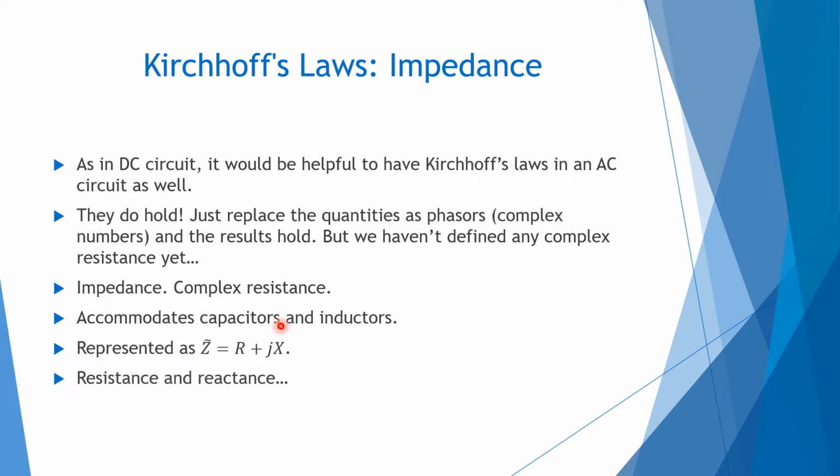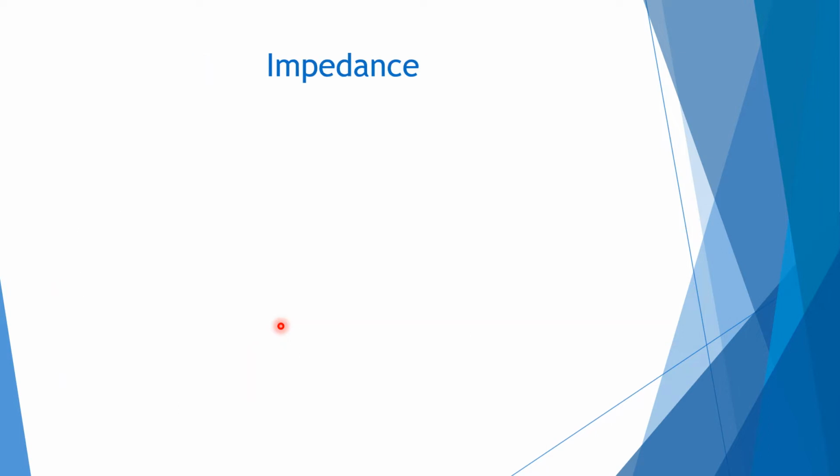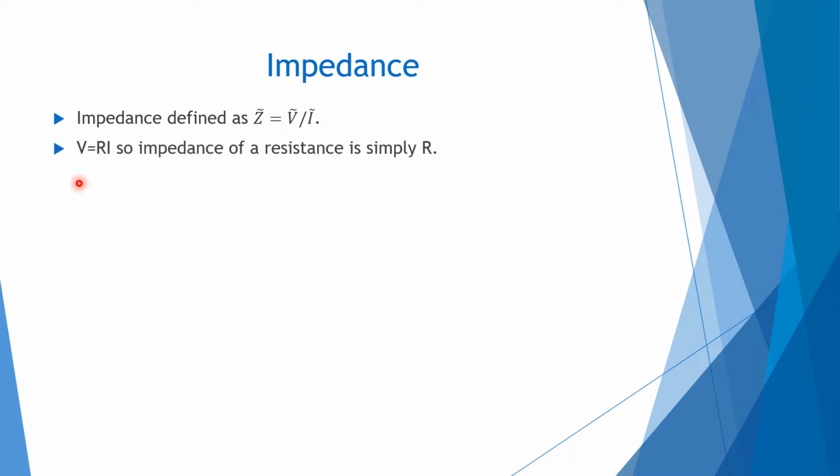We will see what the reactance means. So now by the definition of phasor Ohm's law, Z is V over I, all are complex quantities. So suppose we have a resistor, so we don't even need to put the tildes because V equals IR. So R is simply the real value R. There is no phase shift for the impedance of a resistance.